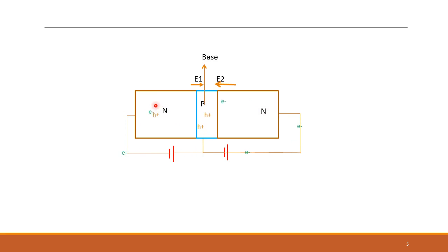So this is the n-type material which actually emits the electrons into the base where it becomes a minority carrier and just goes through and gets swept across the base-collector junction. Since it emits electrons, it's called the emitter, and since this collects the electrons, it's called the collector. So we still have the same emitter, base, collector concept, except that the dopings are N, P, and N instead of P, N, and P.